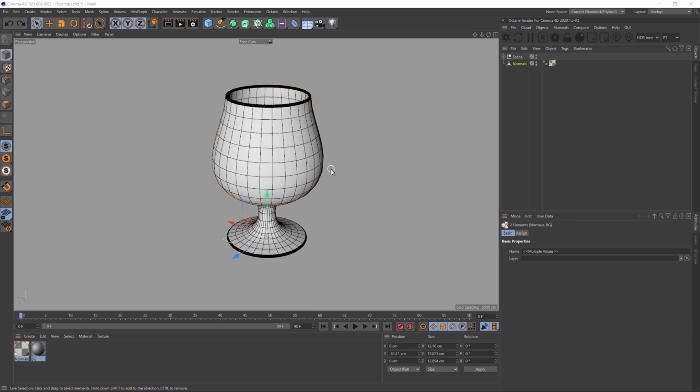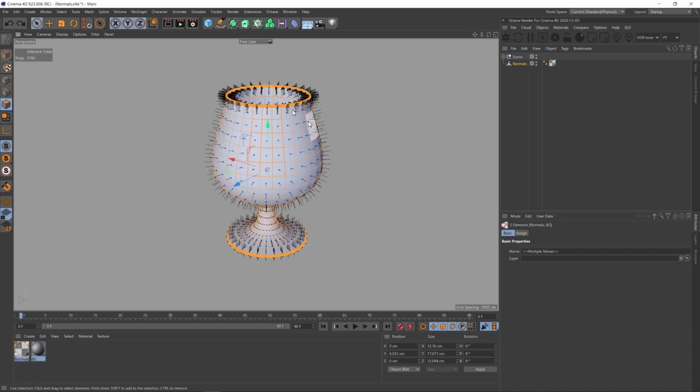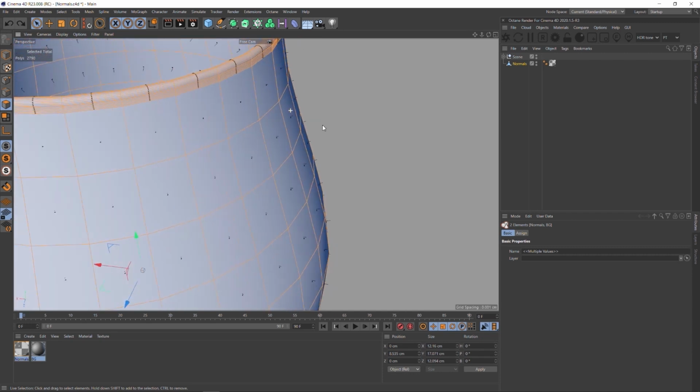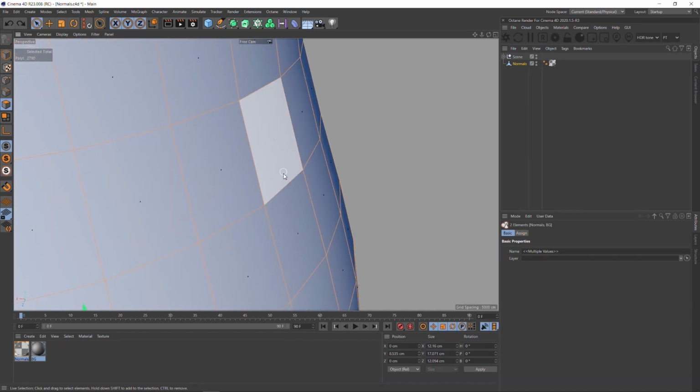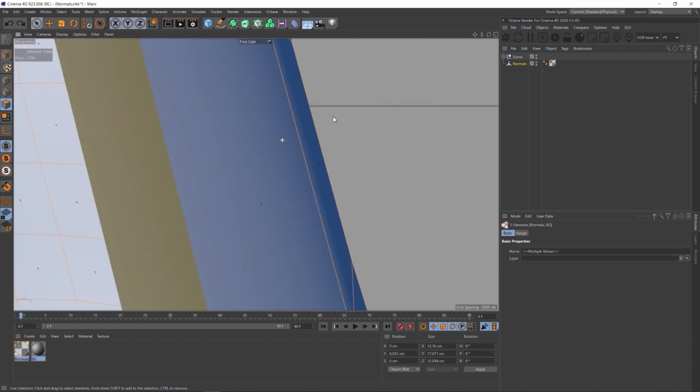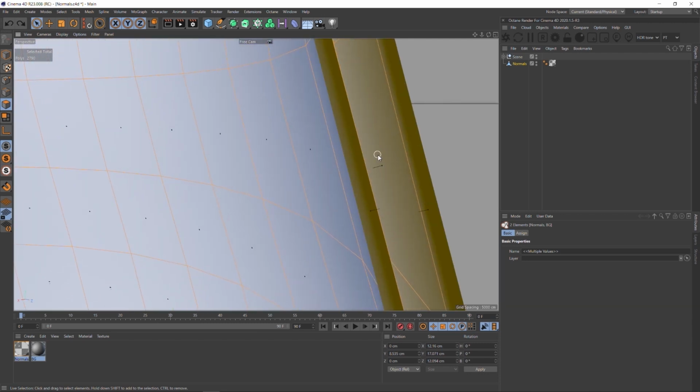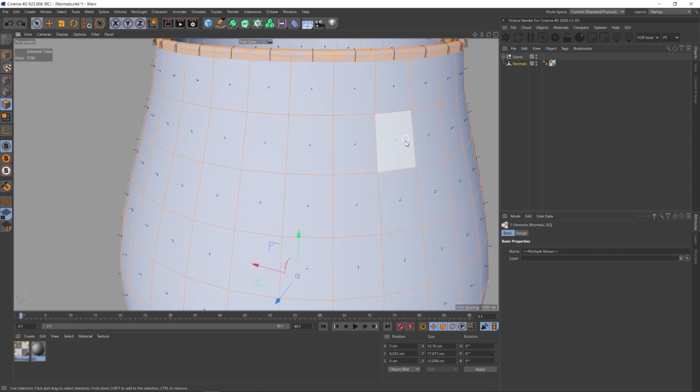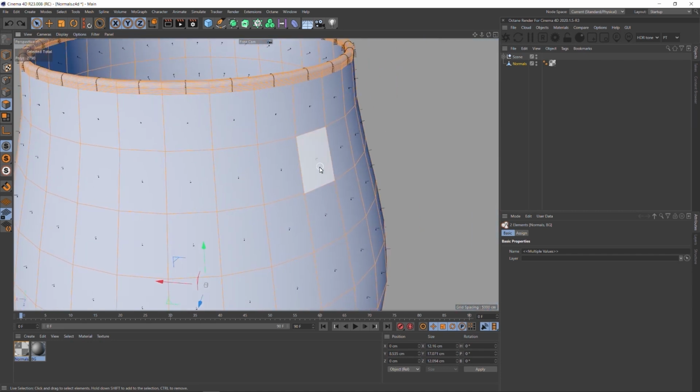All right, so next issue we're going to talk about is normals. Now, I'm going to go into this assuming that you know what a normal is, but let's just take a look at what we've got on this model. So in Cinema 4D, if your normals are facing the wrong direction or you're looking at the backside, they're blue. If they're facing the correct direction, you'll see orange on the outer faces. Now, you want your blue side to be facing the inner volume of the mesh.